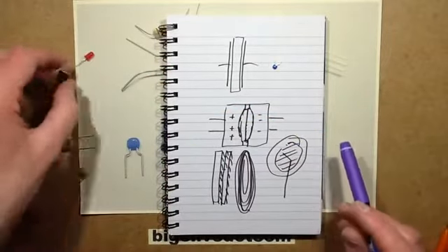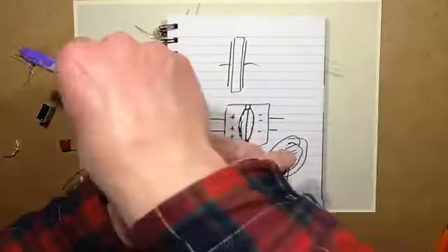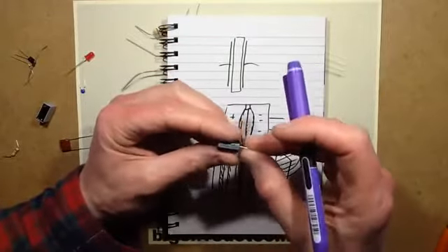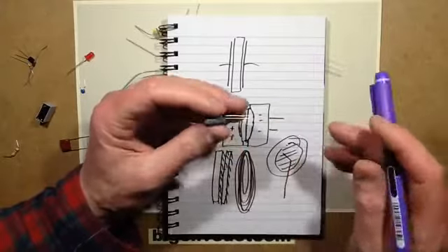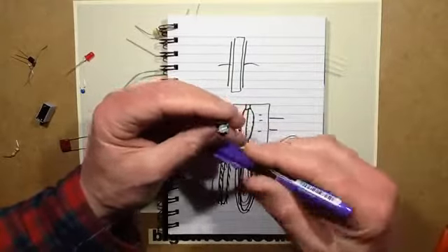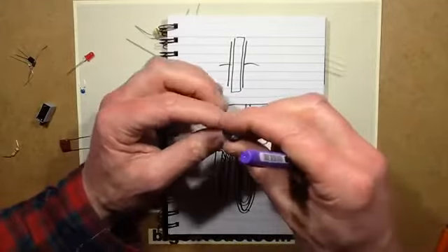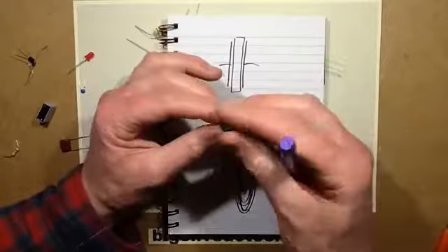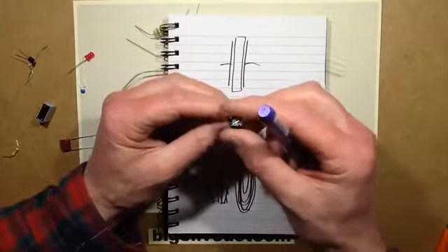So, electrolytic capacitors are one of the more exciting capacitors, and I don't mean that in a good way. To achieve such a high capacitance, they contain a liquid electrolyte, and they have a very thin foil inside. To create an extremely thin insulator, they form an oxide layer on the aluminium foil in there.